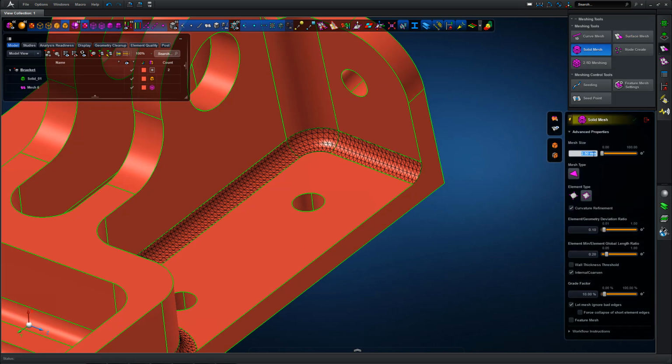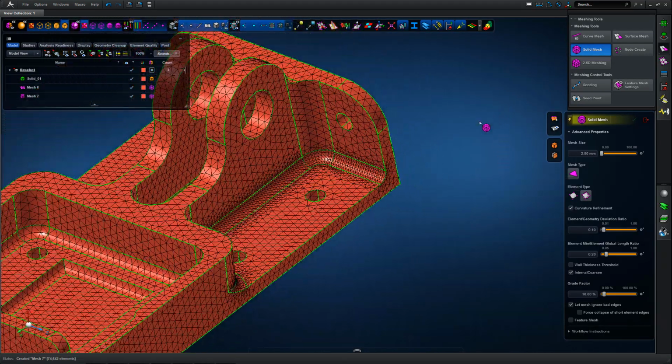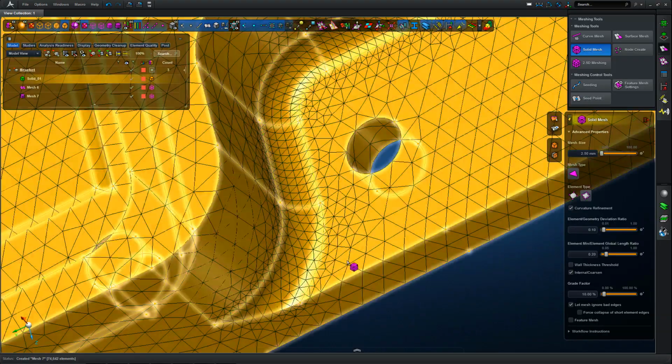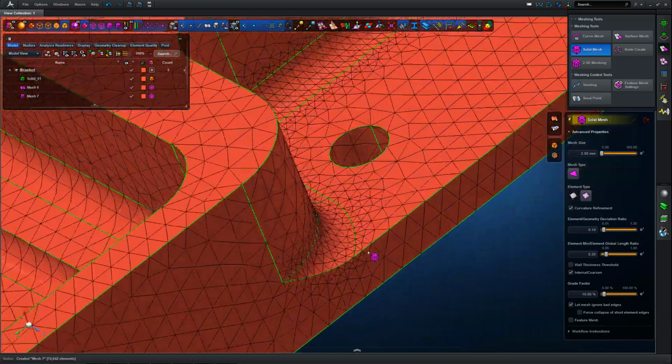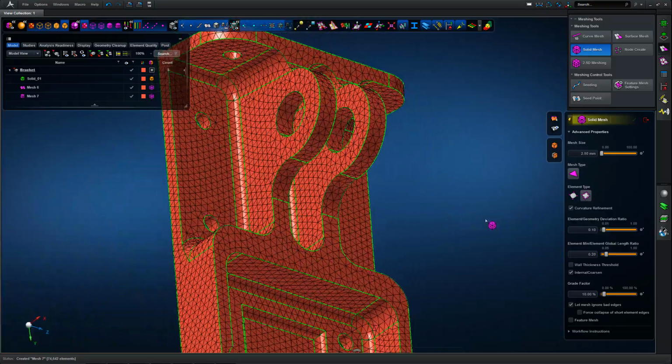With that surface mesh defined, a seed mesh effectively, we can go back into the solid mesh algorithm with the 2.5mm element edge length and mesh the structure, but it respects the 1mm surface edge detail at the fillet features where we wanted a finer mesh definition.